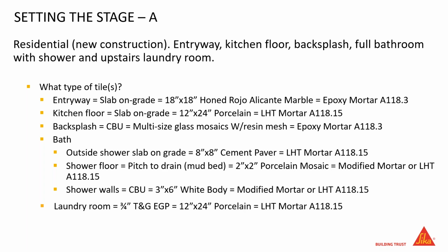Outside shower slab on grade, or did I write outside shower? Outside shower shouldn't be slab on grade. I apologize for that. That is going to be a patching compound with a crack isolation membrane, 8x8 cement paver.